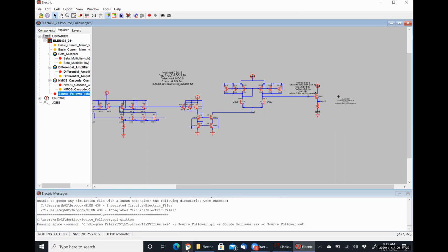Yeah, try it with a capacitor and all that kind of stuff. If it's only happening when it's going from full speed in one direction to full speed in another direction, the key is going to be to mitigate how often that happens. But I understand, if your Arduino dies, your control system cuts out and your self-balancing robot falls, which is what you don't want. It's just a falling robot. Yeah, I might try to take some capacitors from that power supply we built in electronics. They're pretty big.